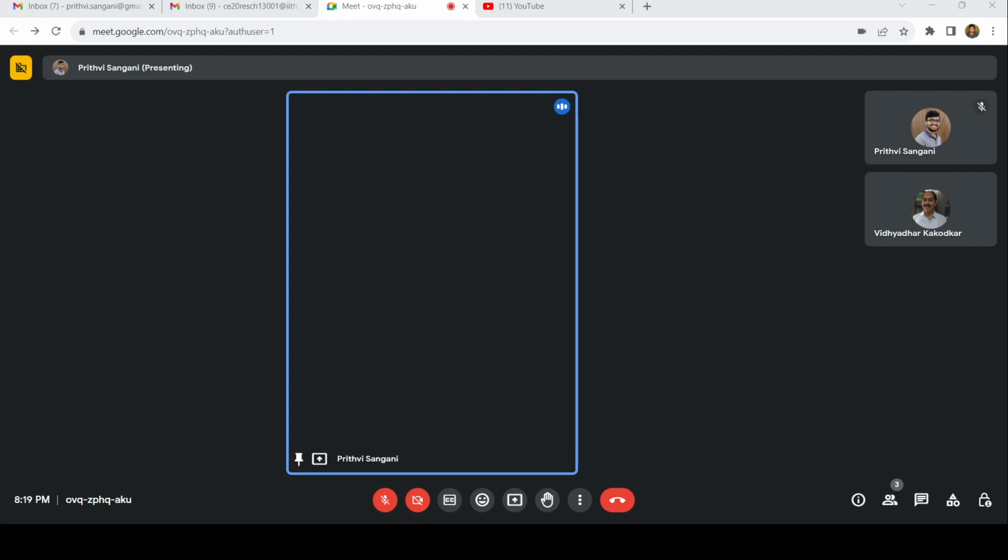So delta 1 is nothing but sigma Fi Ui Li by AE plus, what is delta 1 dash? Delta 1 dash is nothing but displacement over here because of the redundant force F. Okay, so that is going to be F times sigma, sorry, it's not Fi, this is Ui square Li by AE, plus now what is delta 1 double dash?